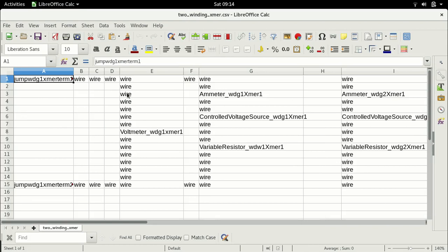Let's assume that this is the applied voltage, and this is our induced EMF, right? And there is some internal resistance. For the induced EMF to be equal to the voltage minus the resistive drop, this current has to be flowing into the winding, right? And the same for this as well.